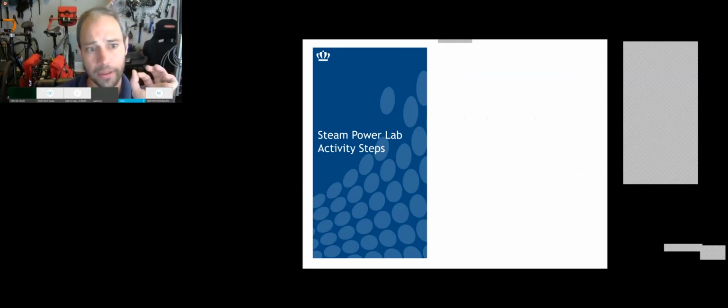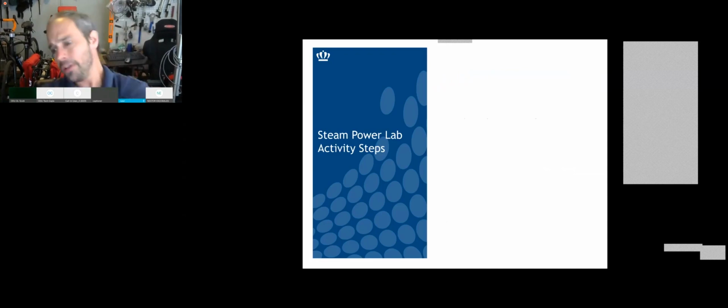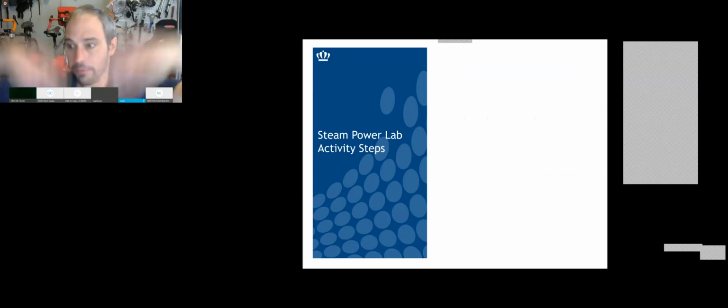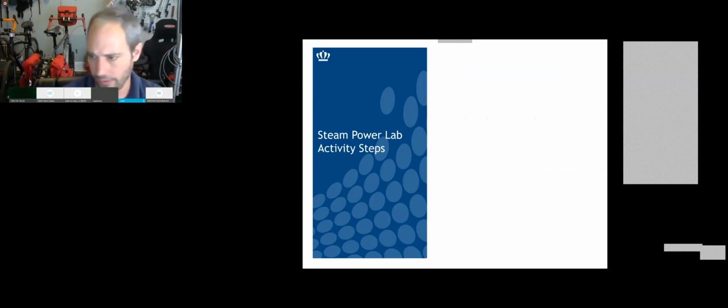But I don't know that I need to, only if we have extra time and we want to fill it. So your activity. Now, if you're a student and you do this lab, I go in the lab first thing in the morning and get the boiler turned on. I let that run for about an hour and a half, 2 hours, because I have to come back and forth, because the water expands when it boils up and heats up, and then it hits the shutoff valve, and you have to release some water to make the boiler keep running, because the heater will cut off when it hits max operating pressure. So it's a back and forth thing for a while. It doesn't happen quickly because it takes a while to boil things.